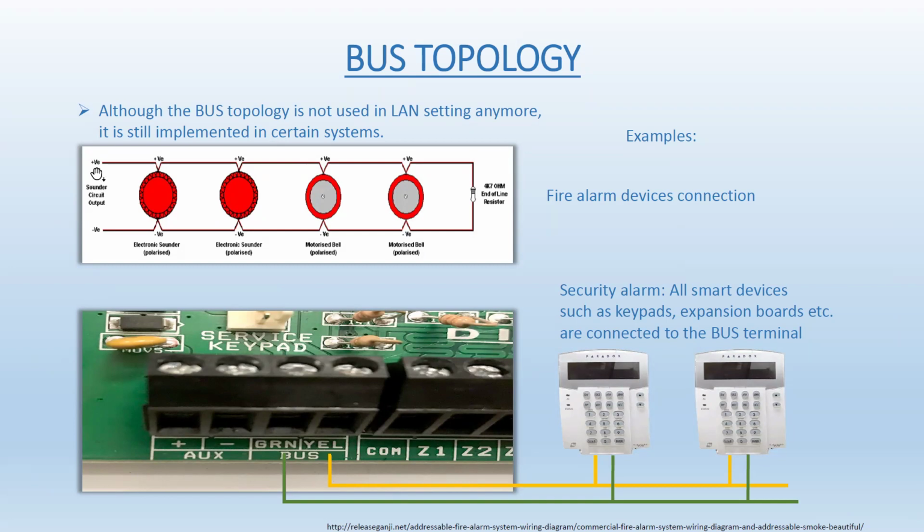So alarm panels, security and fire alarm panels, have multiple zones. So the zones can be named. Here are the smoke detectors in a certain corridor. Here are the smoke detectors in the air ducts going to a certain place. Here is a zone that connects all the pull stations in the hallway that goes from here to there, and so on. Okay? So here is an example of one zone.